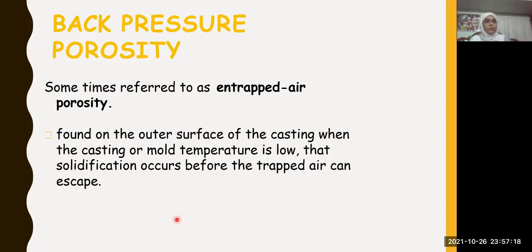Next, you have back pressure porosity because of the air which gets entrapped inside, especially on the outer surface of the casting. This occurs because the casting or the mold temperature is too low. What happens? It solidifies very fast, and when it solidifies very fast, all the air which is trapped inside will not be able to escape out.